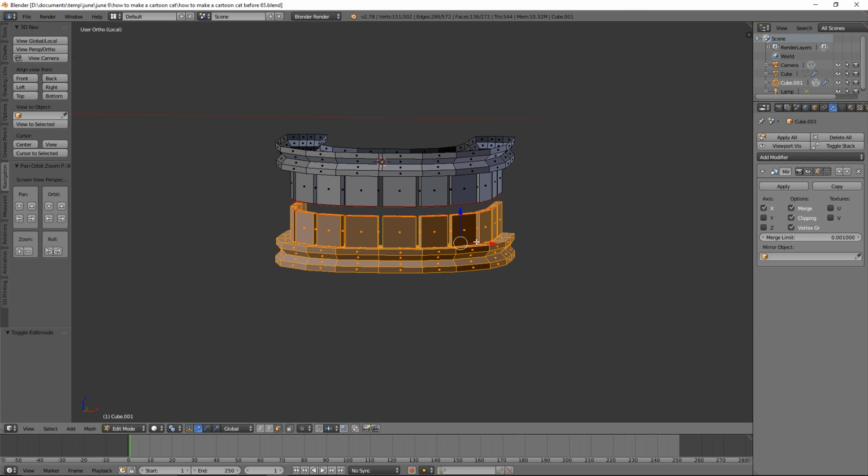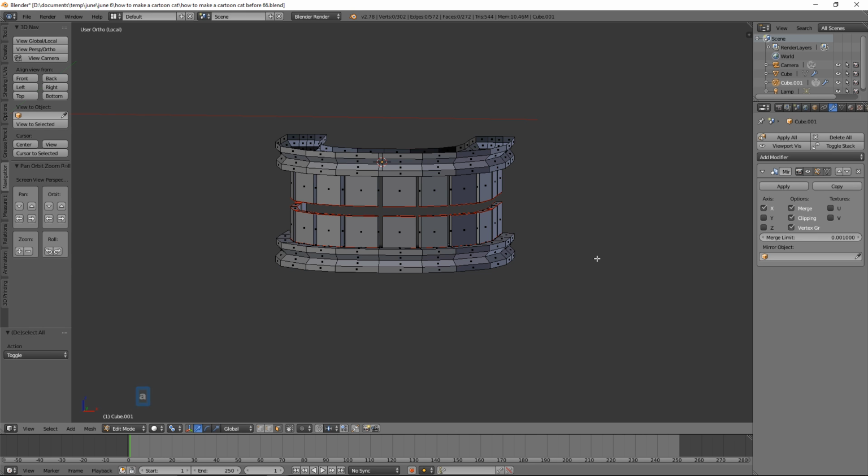Okay, when you look here, you can probably see that the shading here looks different from these teeth here. Most likely the normals are not correct. Normals in Blender, as well as other 3D programs, are basically the direction that polygons are supposed to face. Blender shows us that there's an issue with normals by showing this kind of strange looking shading right here. Blender has a nice way of dealing with this easily, and what that is, we'll hold Control as well as N, and this will recalculate our normals, and now you can see that shading is normal looking again. We'll then press A to deselect.